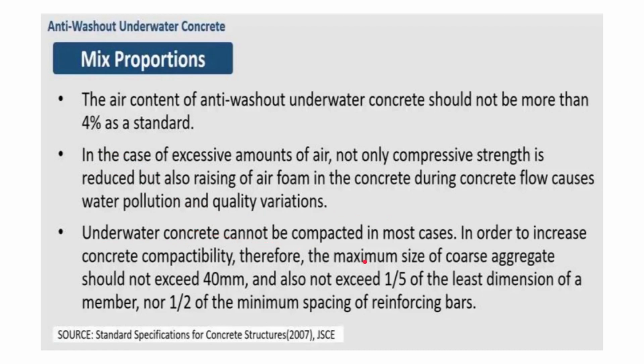Underwater concrete cannot be compacted in most cases. In order to increase concrete compactability, therefore, the maximum size of coarse aggregate should not exceed 40 mm, and also not exceed 1/5 of the least dimension of a member, nor 1/2 of the minimum spacing of reinforcing bars. So these are the factors to be kept in mind.